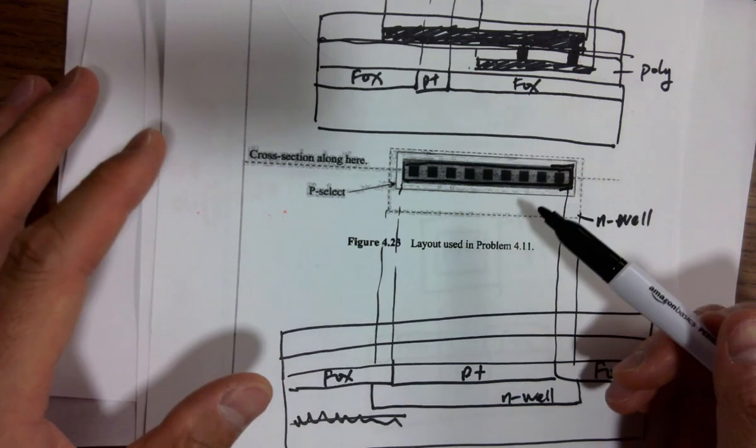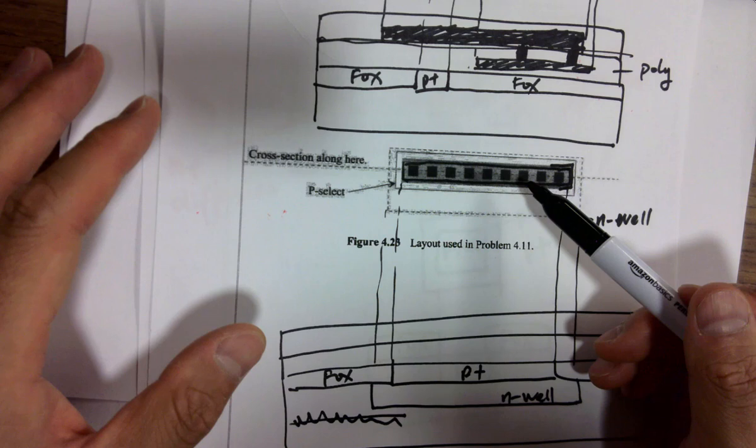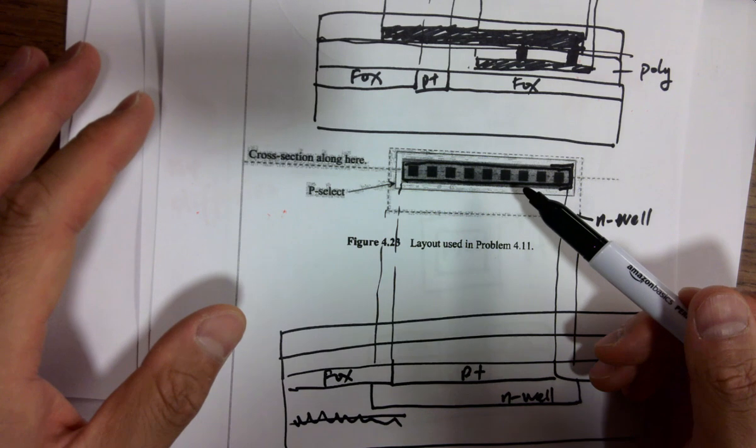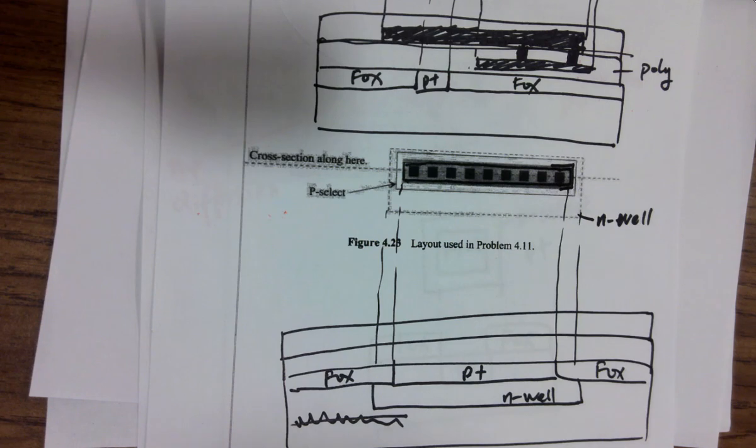Usually the via comes with the metal 1, or metal 1 comes with the via. It's actually a library component. Whenever you grab a piece like this, you can define the length or width of it. And this component from the library is not really asking you to modify it, so it's making things easy for you. It directly has a metal 1 on it, a P plus underneath it, and vias in between them.